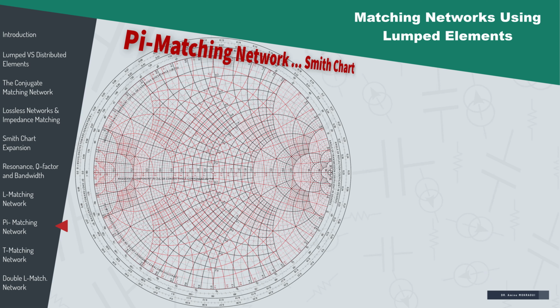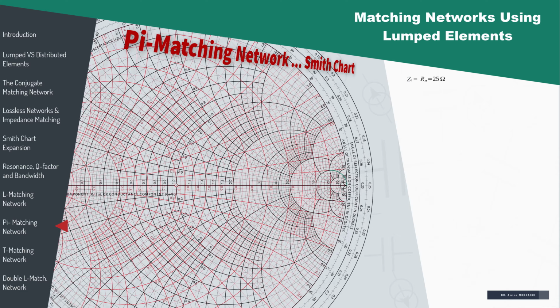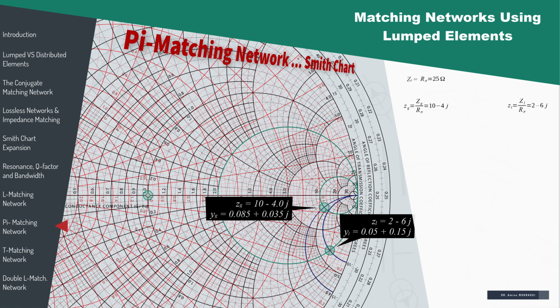Finding the previous results using the Smith chart is quite easy. The resistor R pi equals 25 ohm is used to normalize other impedances. First, we locate Zg and Zl and R pi. Obviously, the latter will be at the center of the Smith chart. We have lowercase zg equals 10 minus 4j and lowercase zl equals 2 minus 6j.